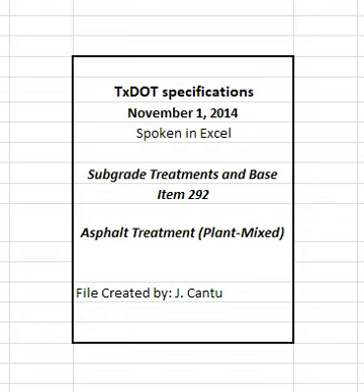Control the mixing time and temperature so that substantially all moisture is removed from the mixture before discharging from the plant. The engineer may perform TEX 212F, Part 2, to verify that the mixture contains no more than 0.2% moisture by weight. The sample will be taken immediately after the mixture is discharged into the truck and tested promptly. 4.3 Hauling operations. Before use, clean all truck beds to ensure that the mixture will not become contaminated. When a release agent is necessary, use a release agent on the department's MPL to coat the truck bed.